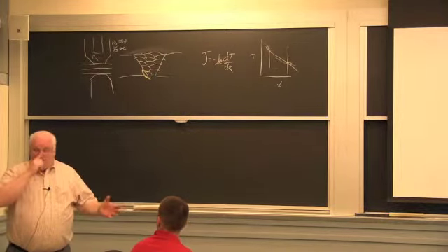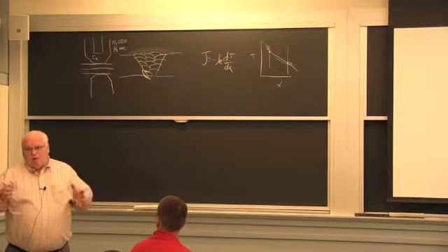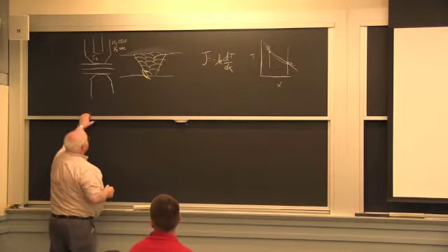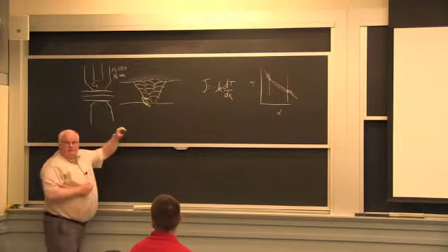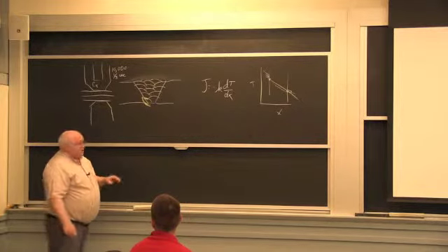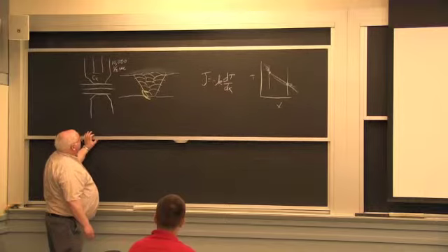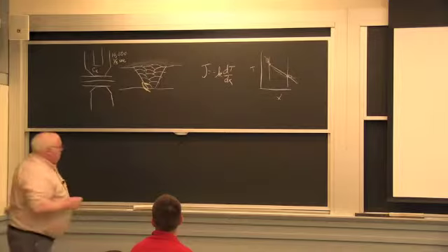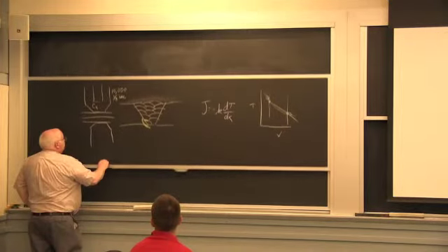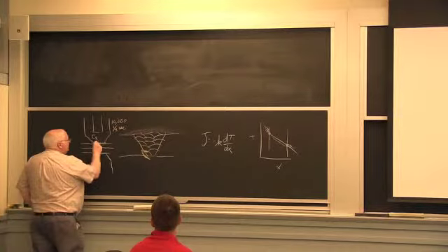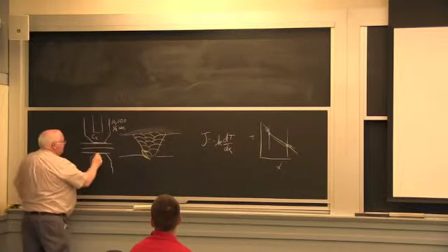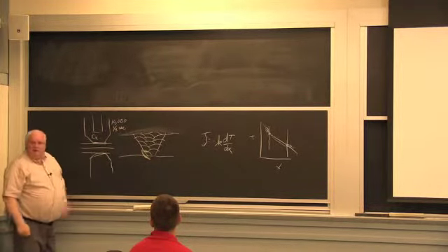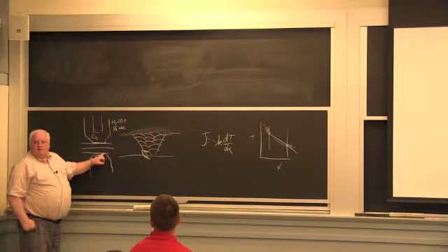When it started in 1980, they were getting about 200 spots. By 1990, they were getting about 2,000 spots. But one of the things they did, they changed some of the steel sheet surface, the galvanizing, and they went to thinner gauge of zinc. One of the more important things is they decided to do maintenance on their tips and on their equipment. One of the big problems here was not that you couldn't get 1,000 if everything was aligned, but if you came in and this thing was skewed at an angle, and so you're really making contact right here, you get a real hot spot. And that was what was destroying things.